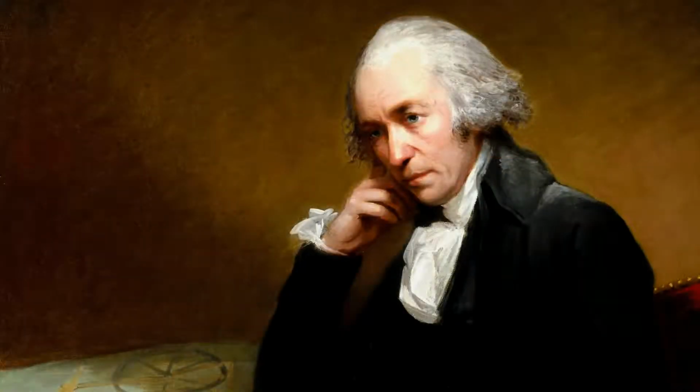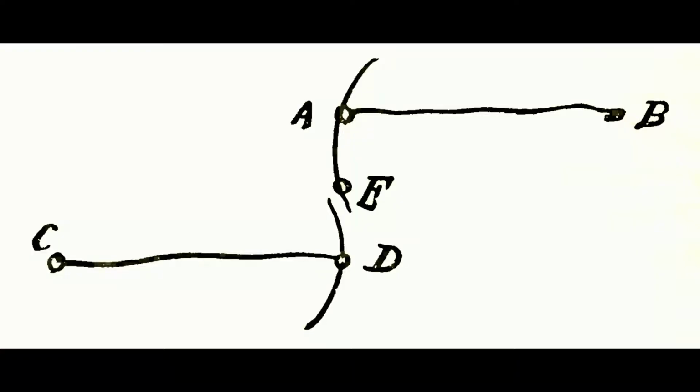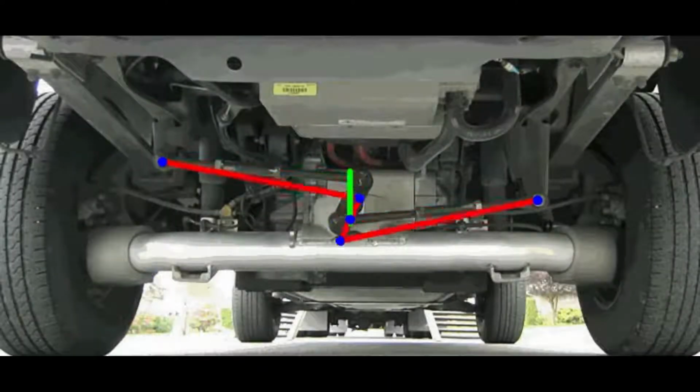James Watt's parallel motion linkage, invented in 1784, is one of the examples that makes an element move along a given path, here a straight line. It is still used in the rear axle of some car suspensions, for instance in a 20-year-old Ford Ranger. Watt was very proud of his invention. But unfortunately the center of the short vertical rod moves along just an approximately straight line segment.